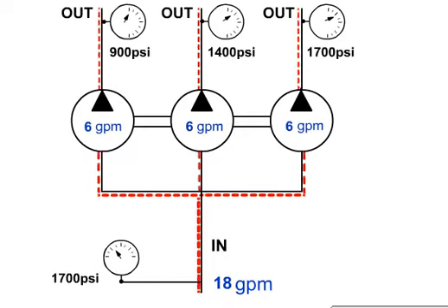The gear-type proportional divider can divide the flow into two or more flow paths. The positive displacement of the gear sections produces a constant division of the flow, even if the loads and pressures in the output circuits vary. The output flows are proportional to the input. As the input varies, the output flows will vary proportionally.